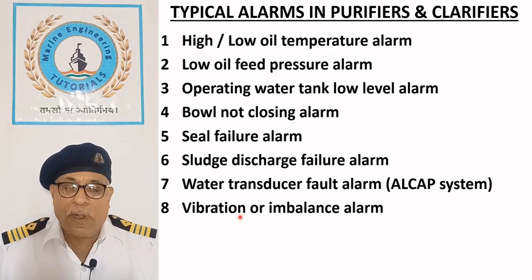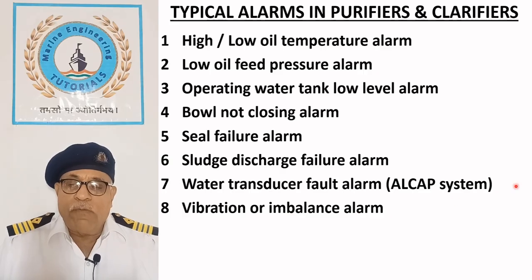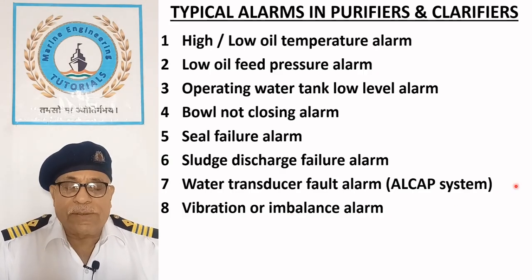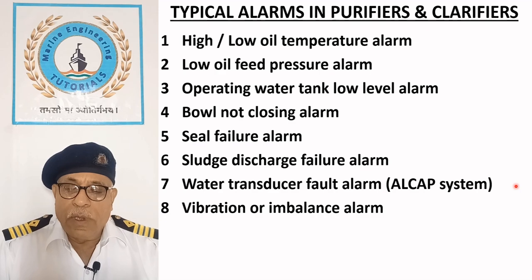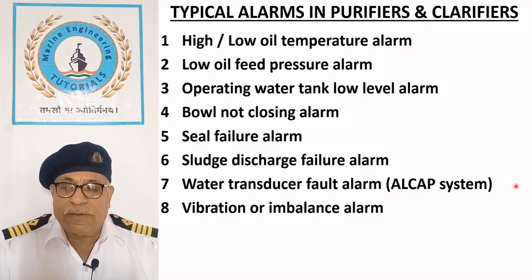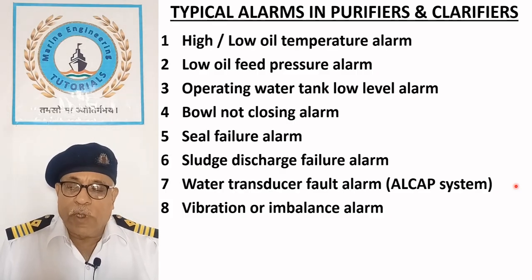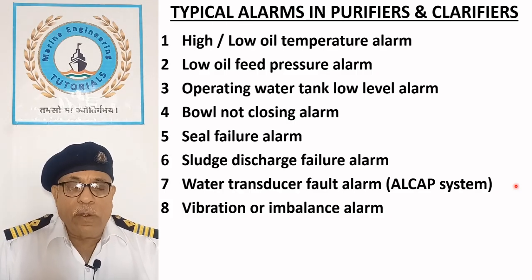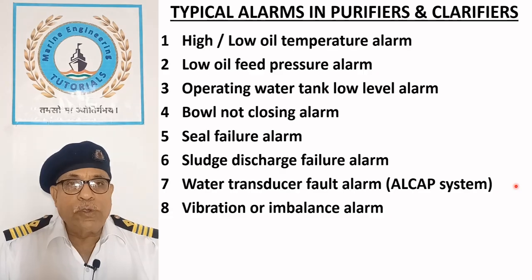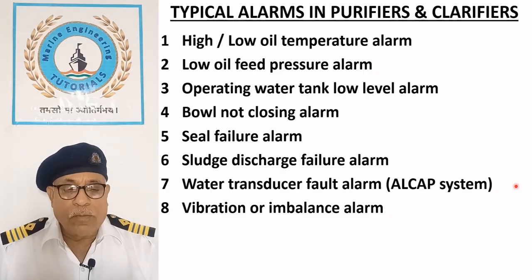Vibration or imbalance alarm. If vibration levels rise during operation, the vibration monitor detects it and sends a signal to stop the purifier. An alarm is then initiated. Common causes include uneven or excessive sludge accumulation, worn bearings, or loose components.